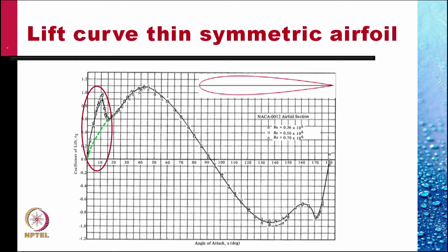This is a very important discovery. In fact, the Wright brothers are credited with this discovery when they suspected that the data they were working with was oversimplified and conducted their own experiments, where they found that the lift produced by airfoils rose sharper with alpha than for a flat plate. The rest of the curve, except for this region, behaves as if it is a flat plate.